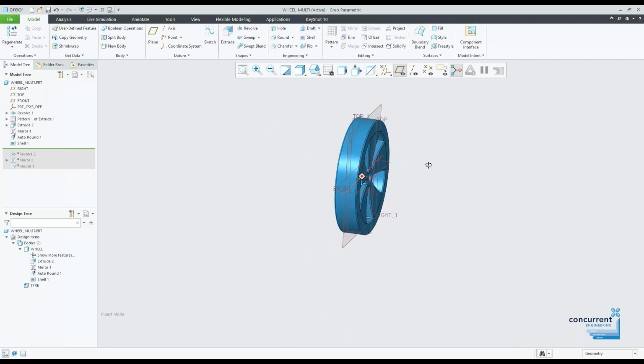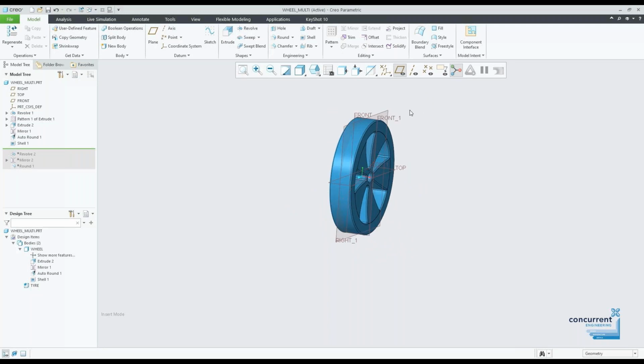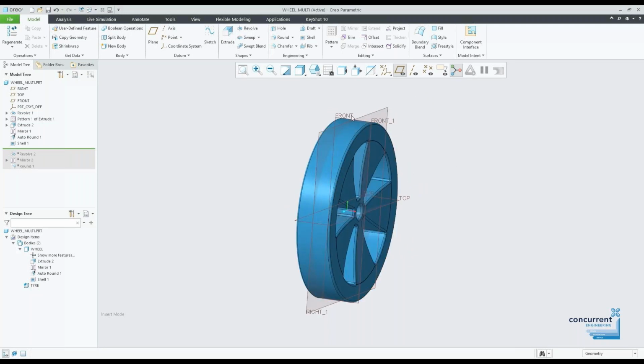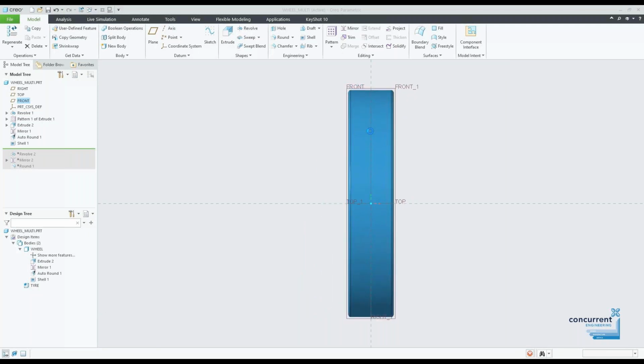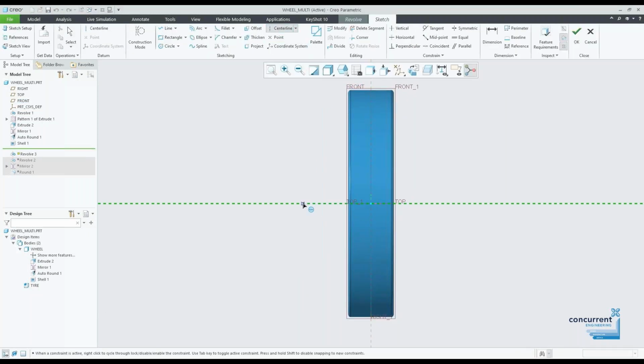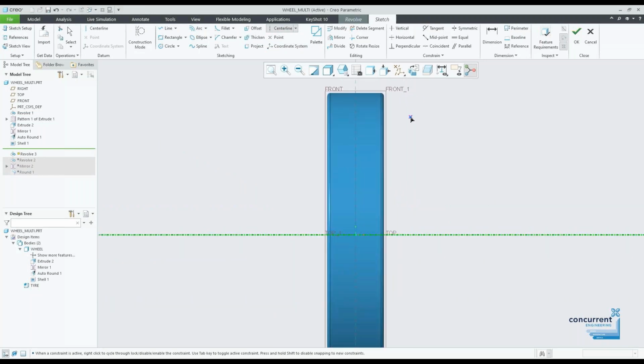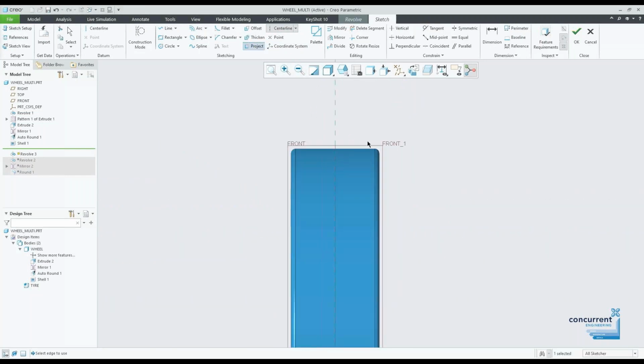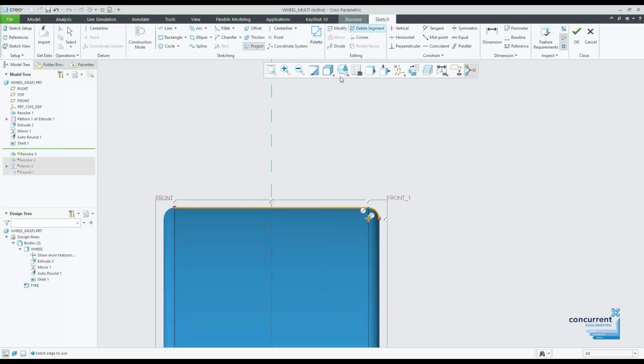The important thing is looking at this new functionality regarding the multi-body. So I'm going to put the second revolve on here and use the actual wheel itself as a reference. So I'm going to select that from plane and go to revolve. Put my centre line in. Always remember the centre line. And then I'm just going to basically project this on the surface here. Delete out the bit I don't need, and then thicken, chain with flat ends.